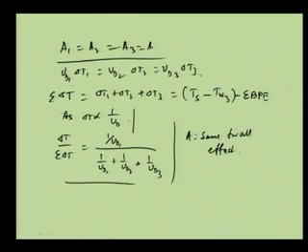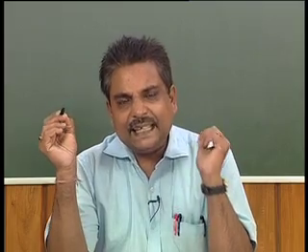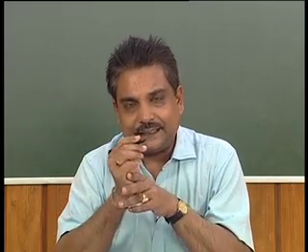So, now what is being done in this case? This way you can find out the delta T. What is being done in these cases in case of design of the evaporators? First, all the steam data are calculated, then some area is assumed to be the same for all the effects, and then based on that we calculate the values of the temperature differences delta T, and once delta T is known, then we will recalculate the areas.